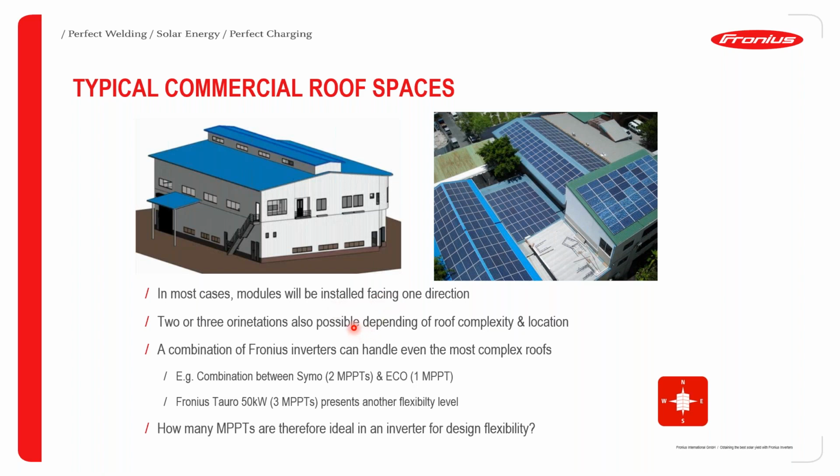design. So in most cases, you also have them prompting the fact that all the modules will have to face in one direction. So 2 or 3 orientations are also possible depending on the roof complexity and location. So depending on the orientation of the roof, we can actually have a combination of Fronius inverters that can handle even the most complex of roof orientations.